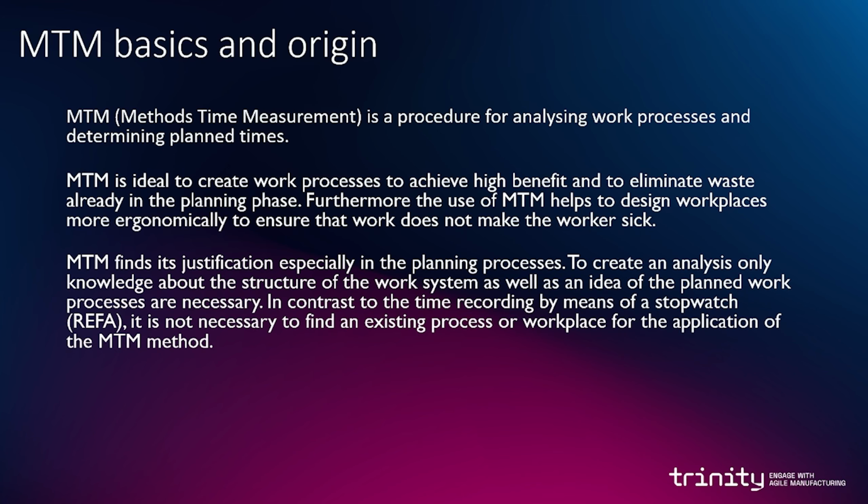MTM finds its justification especially in the planning processes. To create an analysis, it is only necessary to have an idea of the planned work process and the structure of the work systems which will be used. In contrast to the time recording by means of stopwatch, like for example REFA technicians do, it is not necessary to find an existing process or workplace for the application of the MTM method. Therefore, MTM is an appropriate tool to calculate working times before the equipment is available.